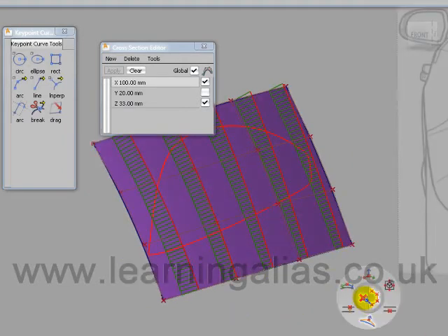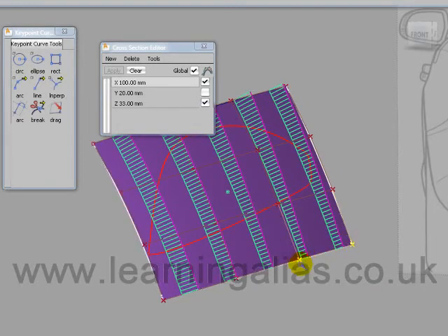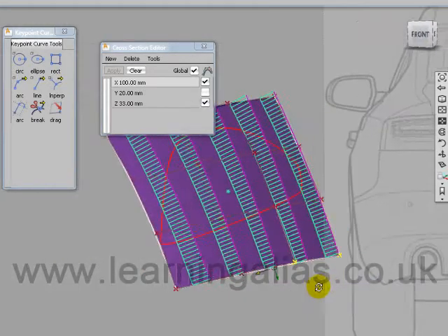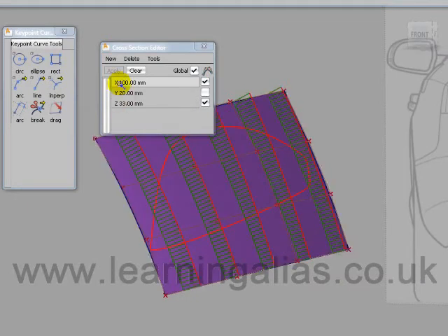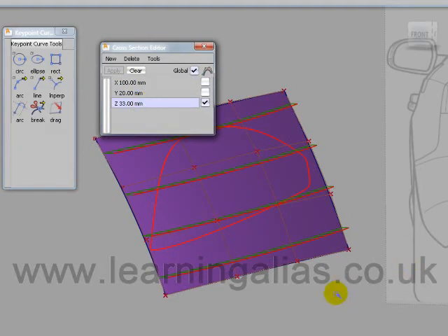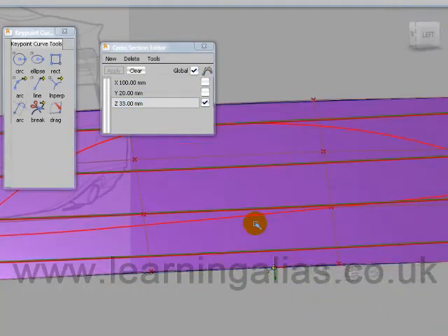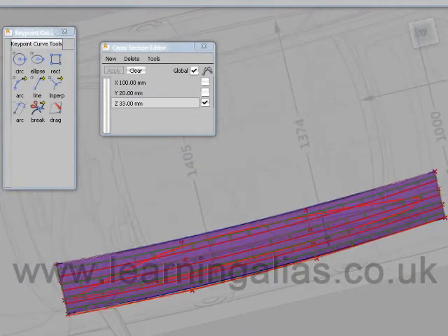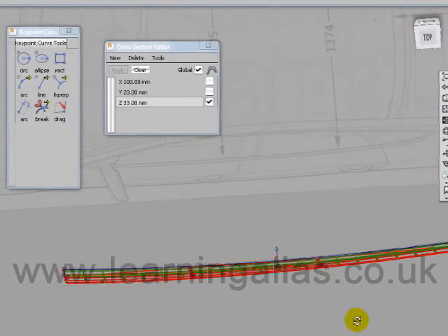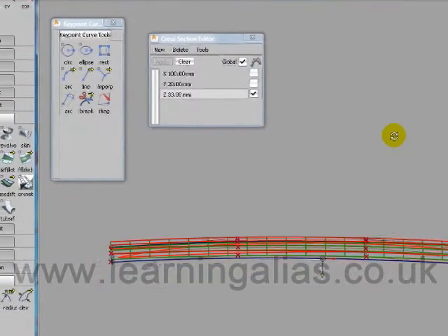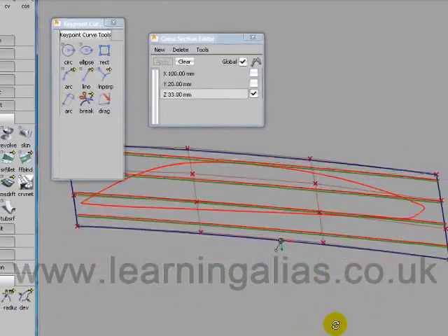It's a bit flat here, so with NUV, I'm going to take those 2 points in, just to get a bit more, match up that curvature there, and it looks pretty consistent. Okay, yeah, that's all in order, isn't it?